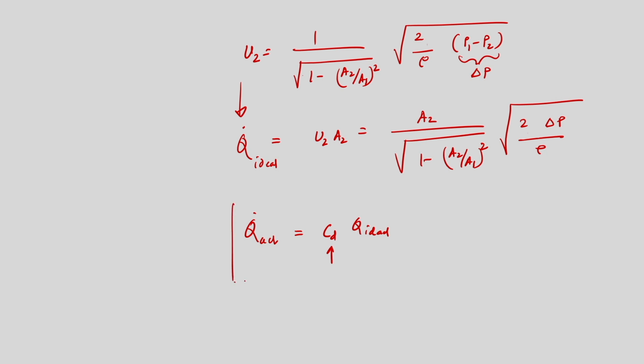So, from there we can calculate the actual flow rate of the internal duct, and this can also be applied in any other fluidic confinement. But two important things are that the measured flow rate is not the correct actual one. To obtain the actual value, we have to multiply it by the CD, and the CD we have to obtain from the literature. Now, this is all about the incompressible flow rate measurement.